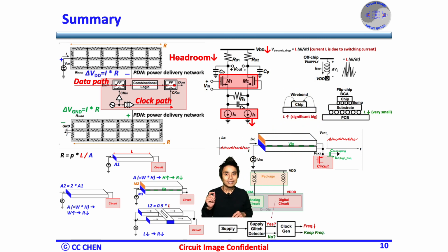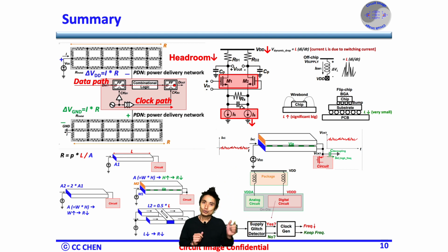Third, a dedicated analog supply for the biasing or the amplifier will prevent the noise crosstalk from the digital supply back from the digital gates. To mitigate the digital timing variation, we still can add the DVFS approach to keep both timing and performance at the same time.